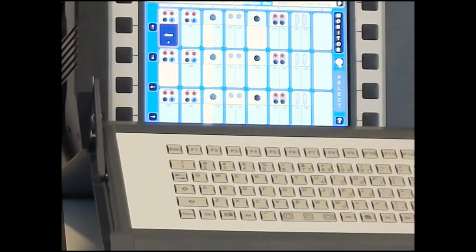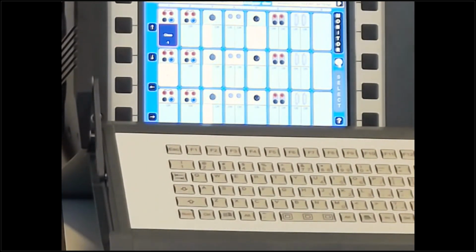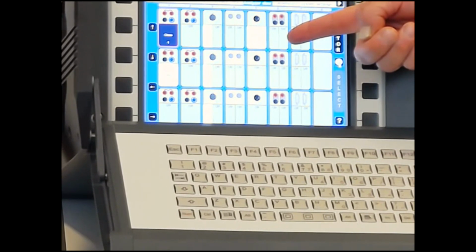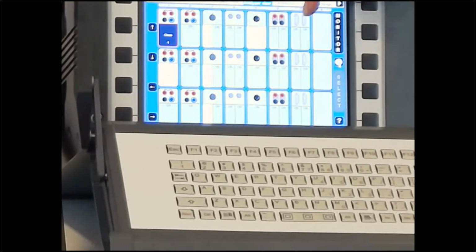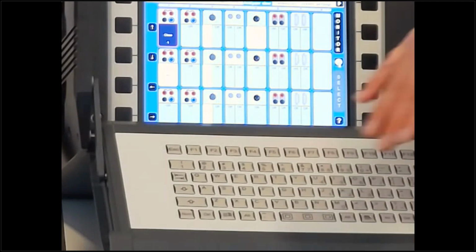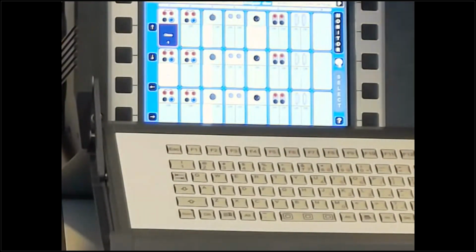Then we have an analog module, which is used for things like motion, but also for dynamic resistance measurement. You can use it for other analog values as well, like voltage, current, motor current, for example. We have auxiliary contact timing, and we have a digital incremental channel. We can read incremental transducers, motion transducers, if we don't want to use the analog channels. So you have quite a big possibility with this setup. But for this breaker, of course, I don't need this big configuration. I would manage with one control module. So in this way, you can adapt your instrument for what you're doing.